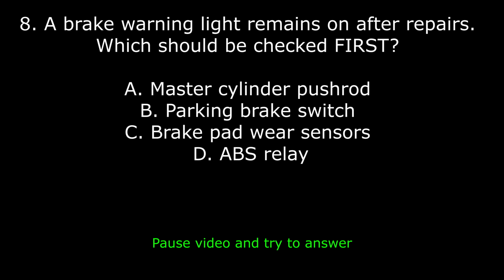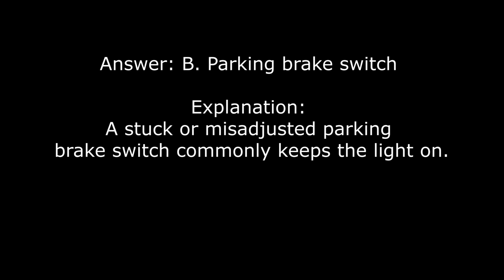8. A brake warning light remains on after repairs. Which should be checked first? A. Master cylinder pushrod. B. Parking brake switch. C. Brake pad wear sensors. D. ABS relay. Answer: B. Parking brake switch. Explanation: a stuck or misadjusted parking brake switch commonly keeps the light on.